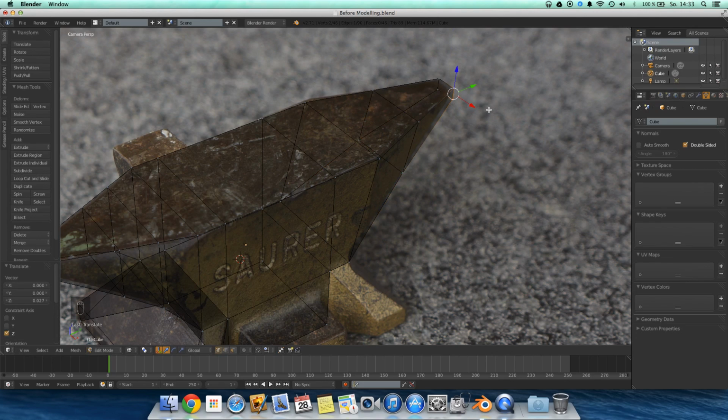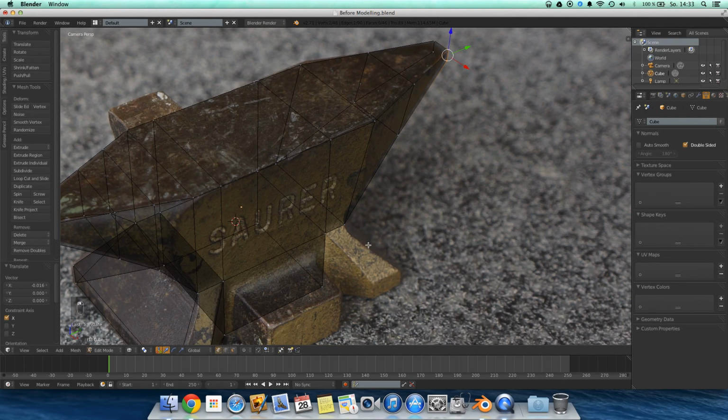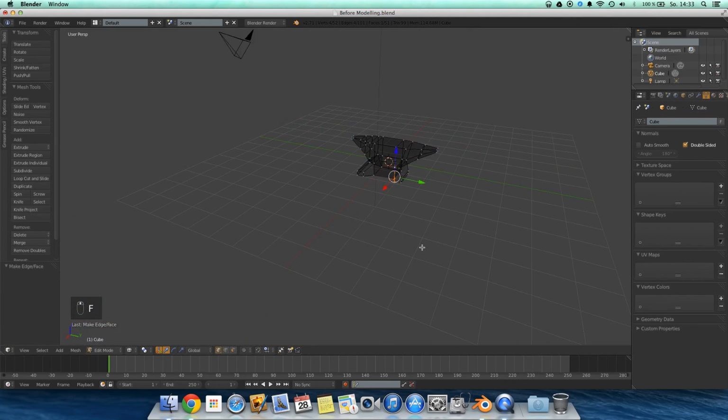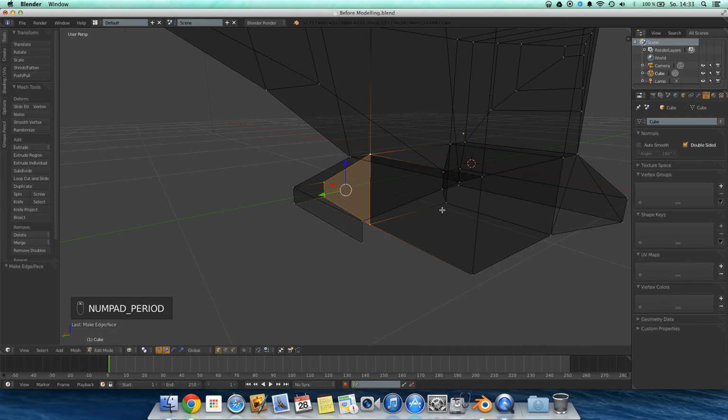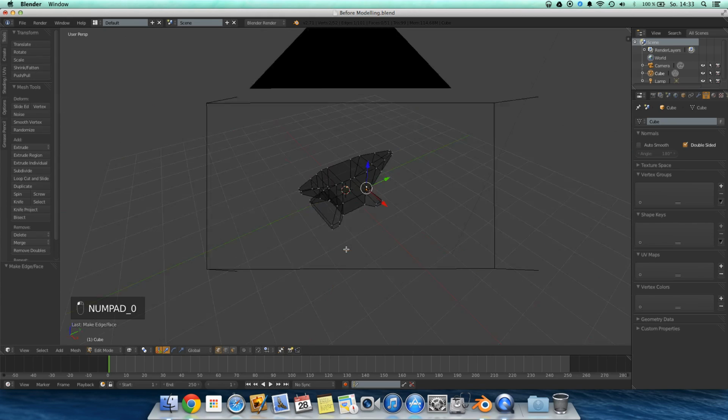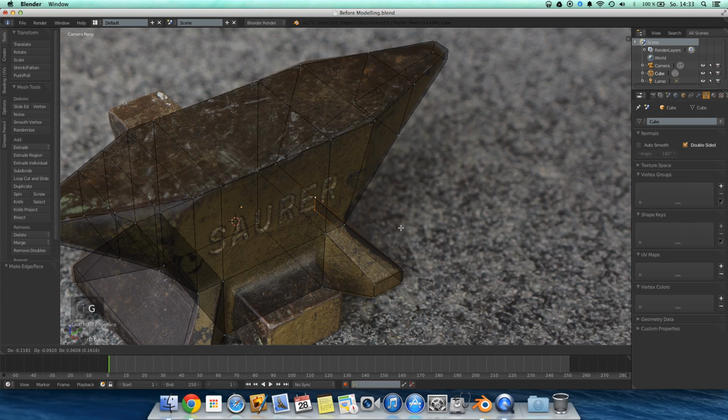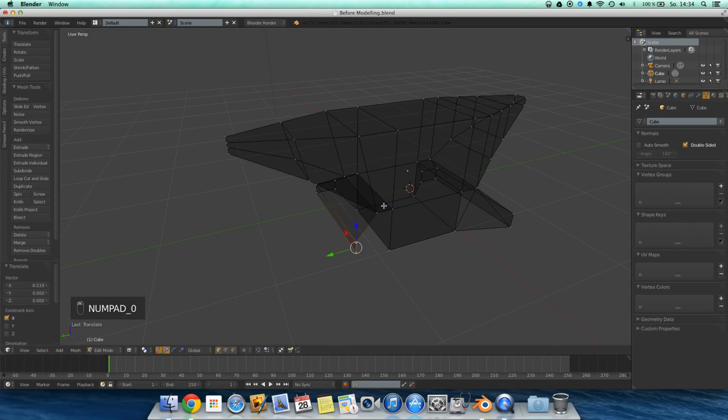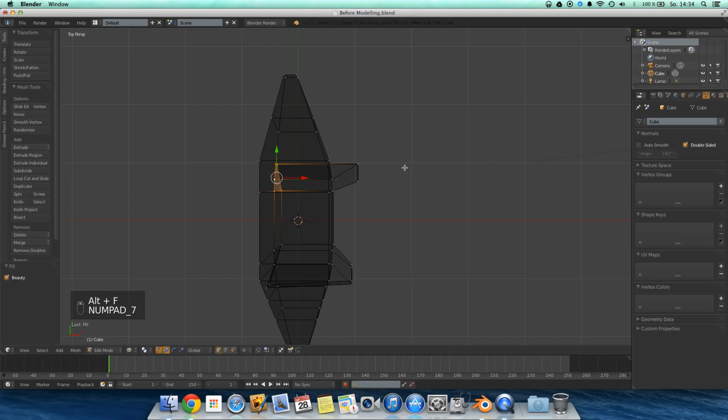manipulate the vertices so they're in the right position, selecting this edge, extruding it out again, selecting those vertices, extruding out, all the time the same thing, selecting those 4 vertices, hitting F, selecting those 4, hitting F. And actually I forgot here to scale this face along the x-axis, but it doesn't matter, you can't see it. So I'm just creating a face now here, but this isn't